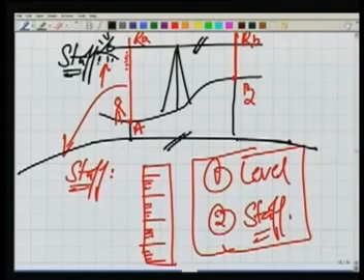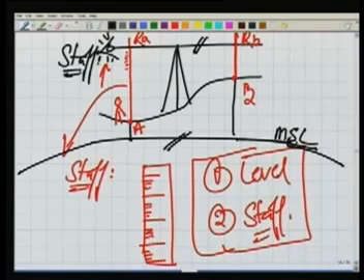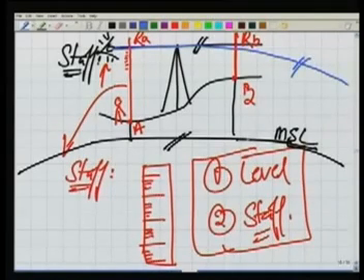But in actual practice, it's not a horizontal surface, rather it's a geoid, or let's say the datum is mean sea level. So if the datum is mean sea level, we should establish over here a line of sight which is parallel to mean sea level. Now how to establish a line of sight which is parallel to mean sea level? That is really not possible. So what we do, we realize it in little pieces.